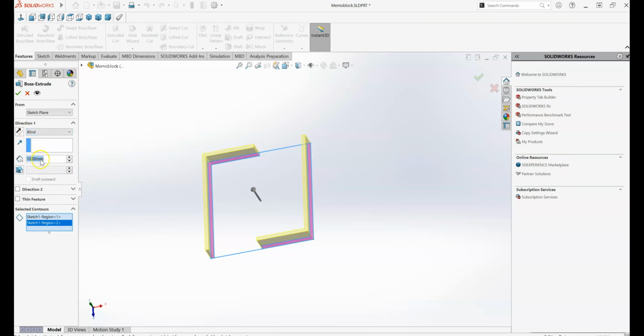Now I want that distance to be 60, but again, rather than typing in a numerical value of 60, what I can do is type in equals global variables, and usually you should be able to see that in a little drop down menu. For some reason it's not displaying properly, maybe the screen recording. So instead I'll just type in equals D and select my global variable here.